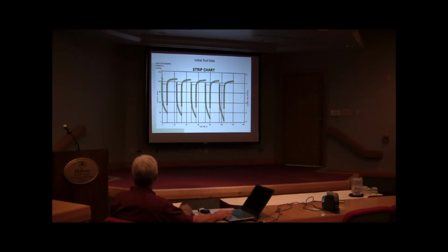What we've got here is they open the well up to flow for some number of hours, and it flowed at a constant rate of about 1.5 million a day. They shut it in for some number of hours, looks like 20 hours. So it looks like probably maybe a 4-hour flow, 20-hour shut-in, 4-hour flow. And you can see that the rates they reported were essentially the same all the way across.